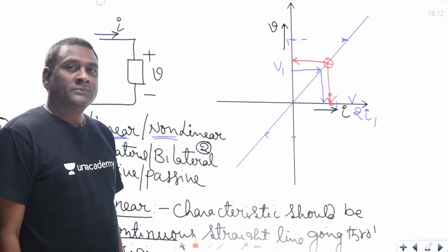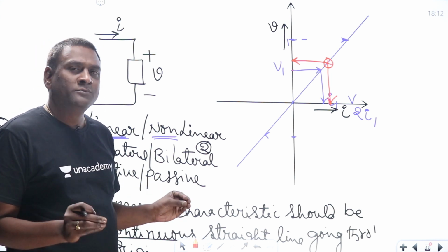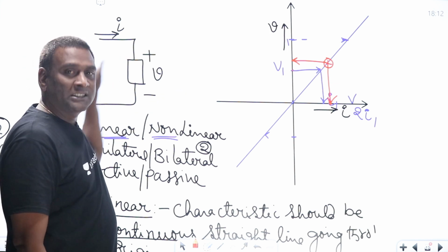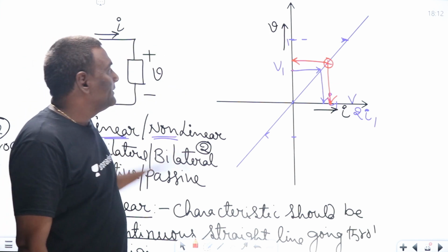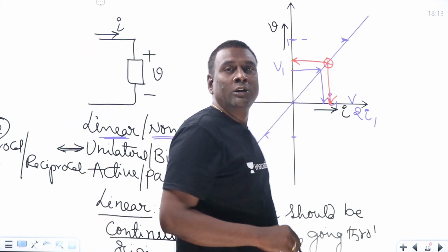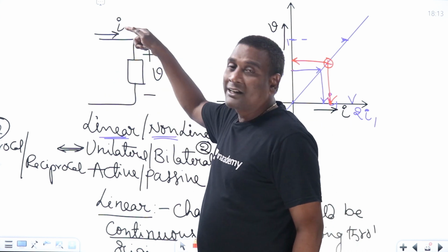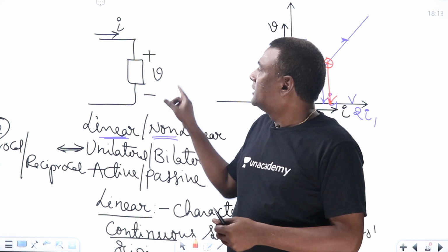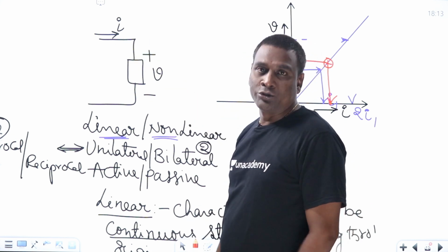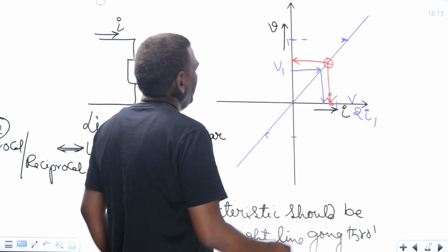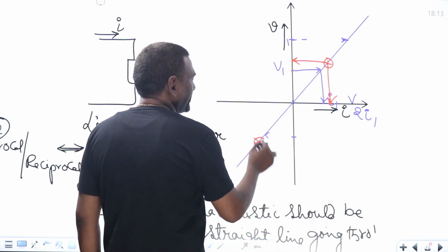You understand my point, right? So simple. First of all, we have to focus on here. Anyway, passive sign convention is followed here. Then, whenever voltage magnitude is positive, current magnitude is positive, meaning that whenever this is positive, net power absorbed is going to be positive because current is entering into the positive terminal of the voltage. Now, maybe if it is operating at this point.